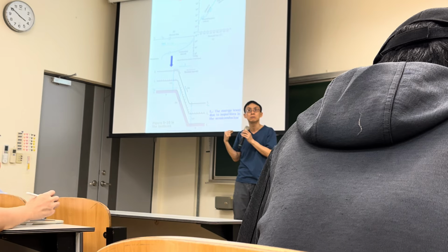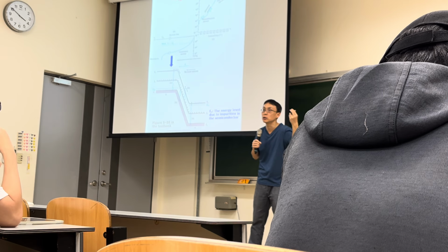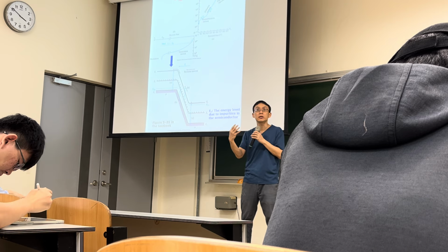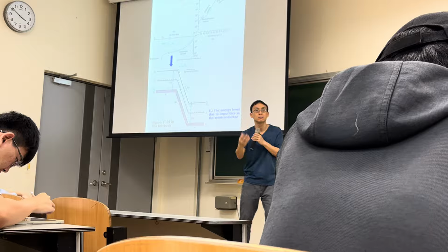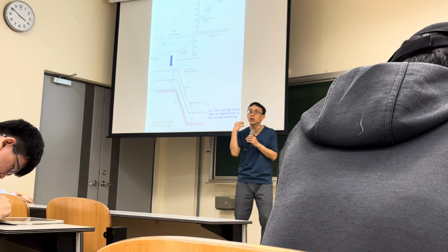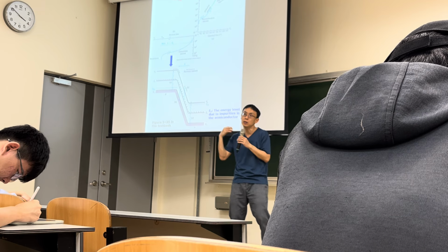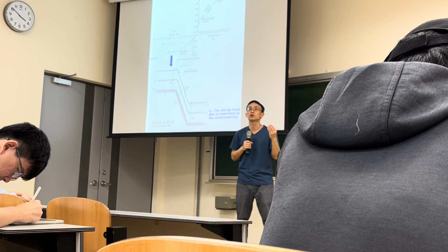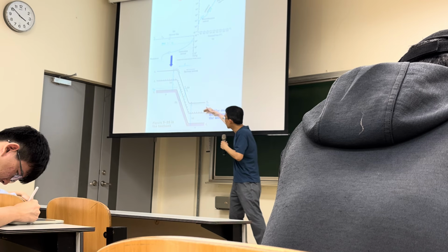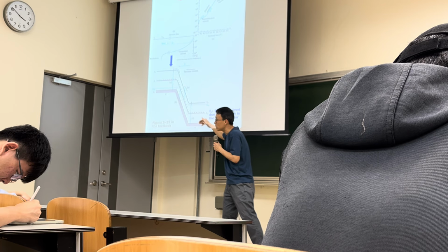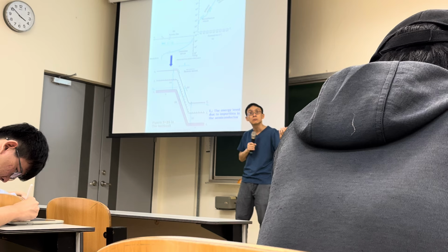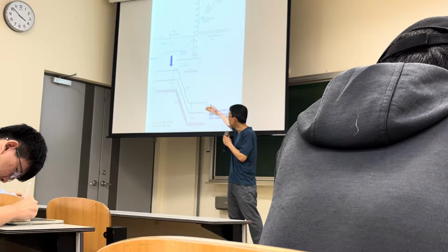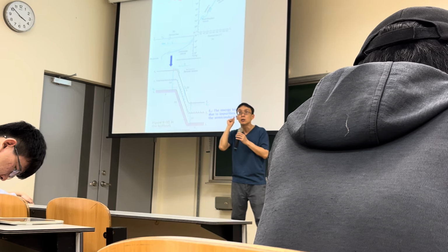The density of states is very different. The density of states is the number of energy states that electrons can occupy. In other words, the valence band can hold a huge number of electrons, maybe 10 billion. But the density of states of the impurity level is far lower than the valence band, maybe 1 million. One is 1 million, one is 100 million. So much difference. So the current from the impurity level and the current from the valence band are so much different. The concentration of electrons excited from the valence band is much higher than from the impurity level because of the huge difference in density of states.